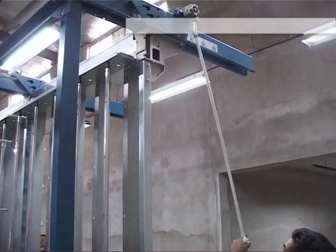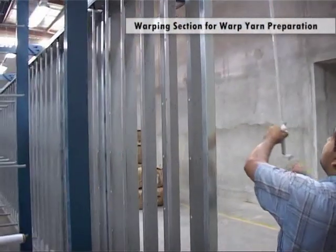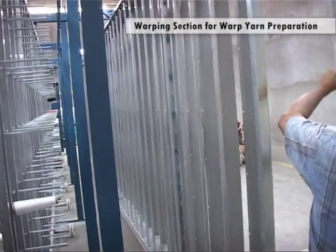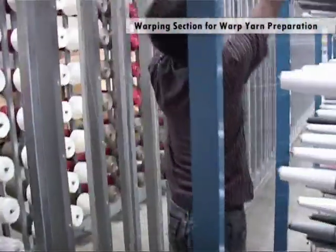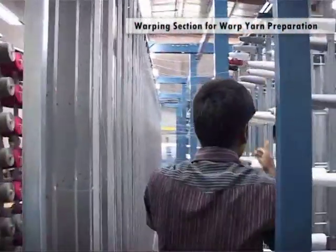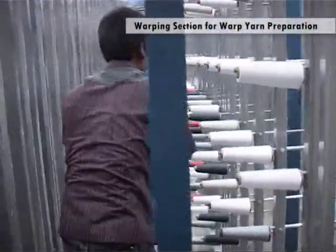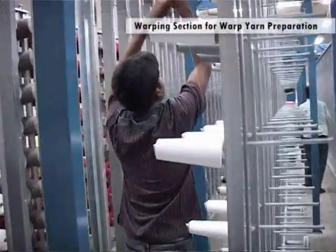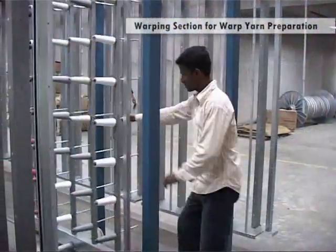Warping is aimed at preparing the weaver's beam to be set up on the weaving machine. Warping carries out the following operations. Creation of a limited number of warp threads. Creation of a warp composed of any number of threads with the desired length. Arrangement of the above-mentioned threads according to the desired sequence. Manufacturing of a warp beam with set characteristics.